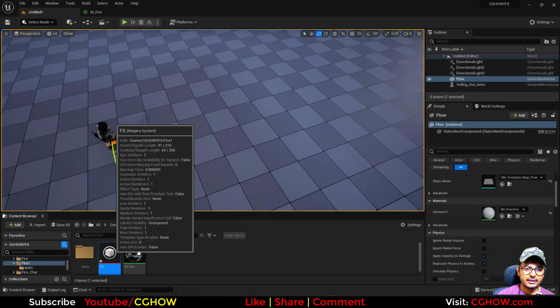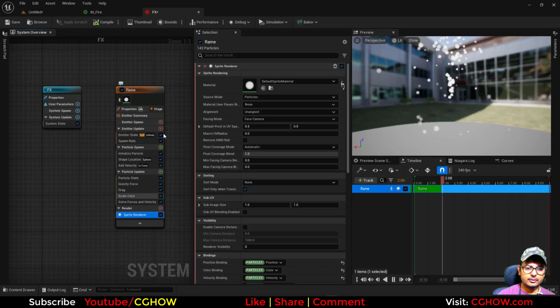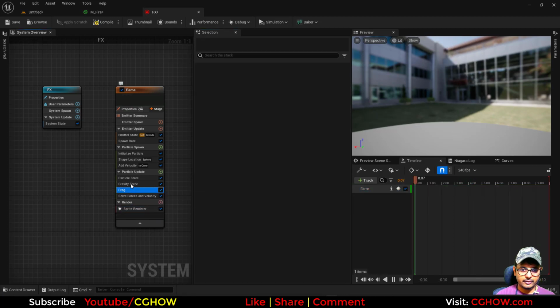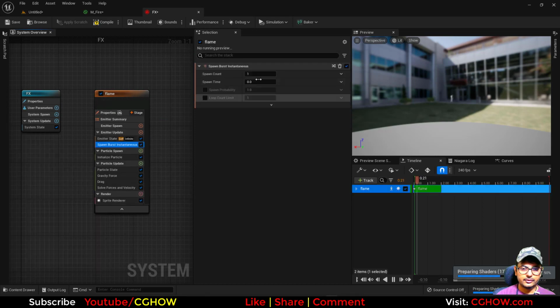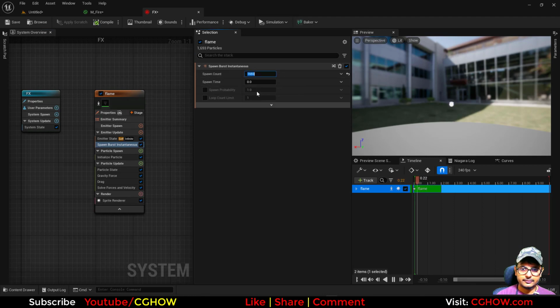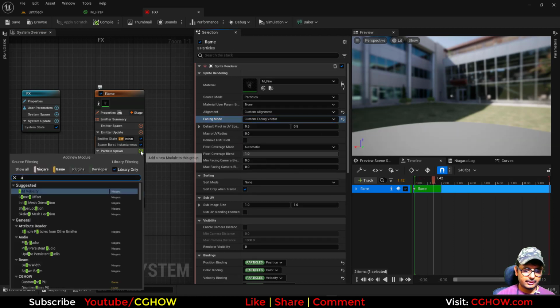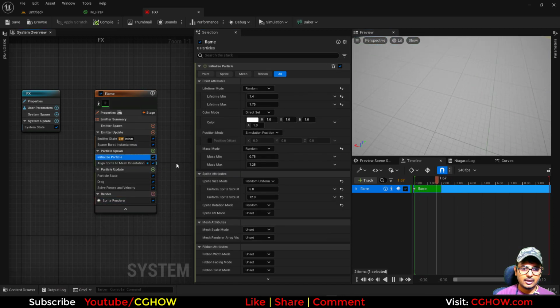And I'll browse this, and in the FX, this will be my flame, and I'll use that material. And I will not use this for now. And let's say you are bursting maybe 3 particles, and you don't have gravity, and I align custom alignment, custom vector, and take the align to mesh orientation on z-axis, and I'll make the size maybe 100 for now.